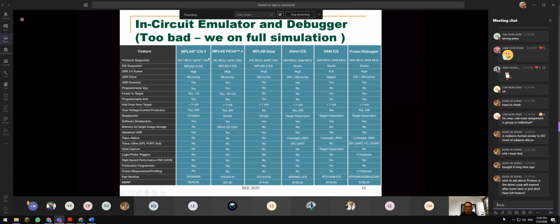What are the differences between the PICkit and the in-circuit debugger? Look at the price of the in-circuit debugger, a fantastic price. It's faster, it's better, and it gives you more breakpoints when you do debugging. You will learn all this later. Whereas PICkit 3 or 4 is for hobbies and student usage. You can burn the code, download the firmware into the microcontroller. I believe you already used this before in your microcontroller processor section. Do you know that PICkit 4 also allows you to have real-time debugging?